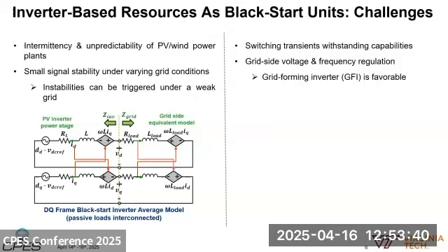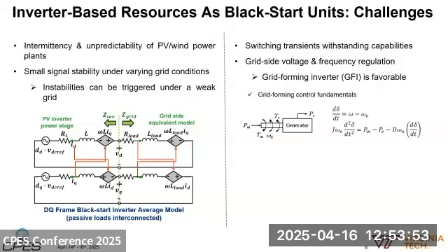However, the grid-forming inverter offers an alternative grid synchronization approach, and it is a promising choice in black start application. The synchronization mechanism of the virtual synchronous generator mimics the power balance of a real synchronous generator. It will transfer any mismatch between the input and output power into a change in the rotating speed, which in turn will reduce this mismatch, as the famous swing equation shows.